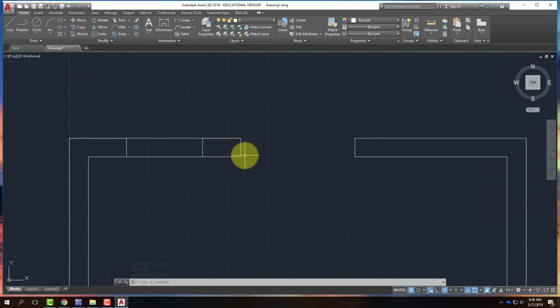It can make the lines darker. It can interfere with snapping later. It can interfere certainly when you export this and build it in Rhino. So it's good practice not to have those extra lines. So instead of drawing this with those extra lines, we're going to use something that's built into AutoCAD that can control where the line is going to start. It's the equivalent of smart tracking in Rhino.